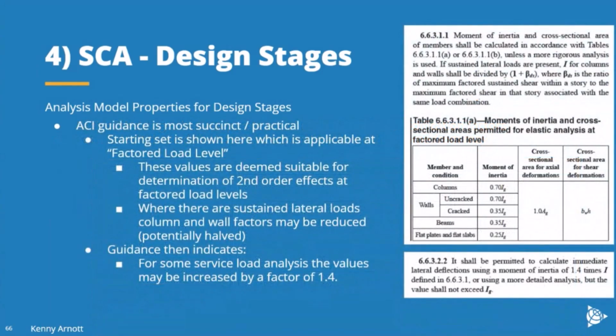And once again, we've taken as lead guidance here the ACI guidance, where in ACI 318 you've got a table which looks very simple, gives some basic adjustments for columns, walls, beams, and flat slabs. Then in the text around that table, you've got information that says this is deemed suitable for combinations where the lateral loading effect is not sustained.